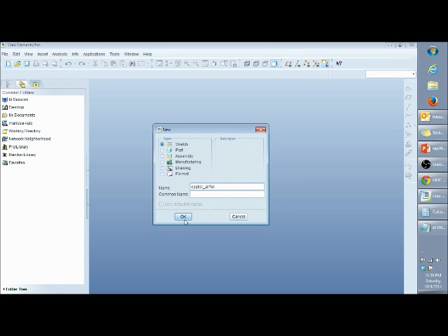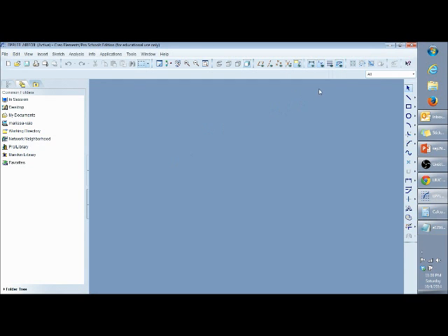There you go. Okay. So now the first step, which is very important, is to create a coordinate system for your sketch. So select it, which was over there, and there, middle click to exit out of it, and so now you have a coordinate system to base it off of. And what we're going to use this coordinate system for is to create a 1-inch line. So select the line tool, go over here, make sure it locks onto the center of that axis, and drag it out.